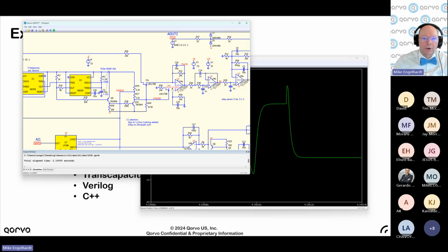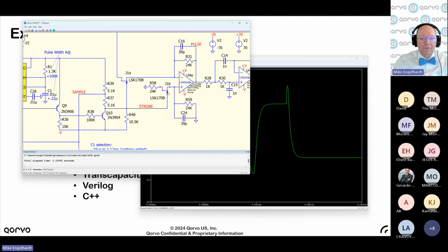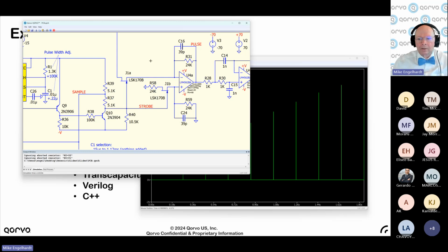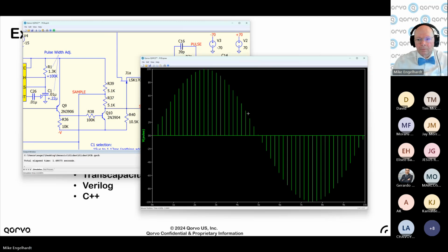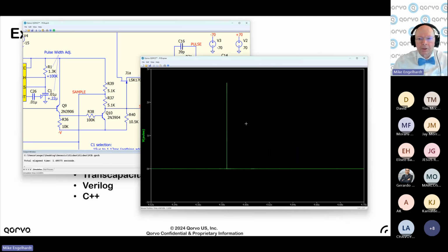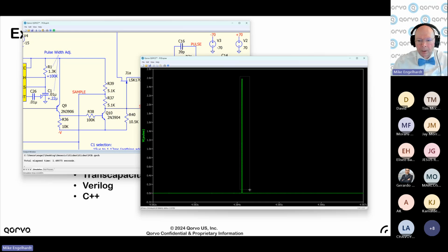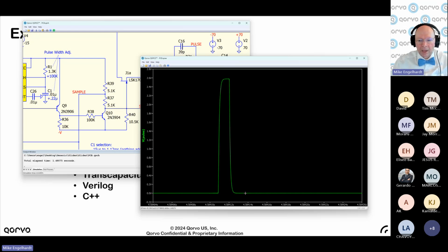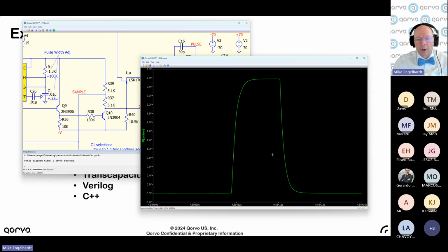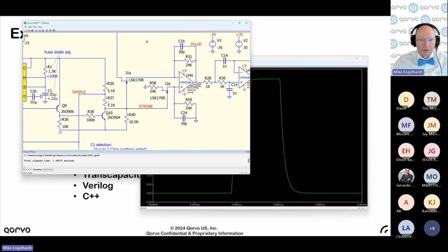Basically, on this node, instead of connecting it to ground, I mock up the same circuit on that. So if this JFET is on, this node is ground. If the JFET is off, it's still ground because it's connected to ground through here instead of through both of them. And then the charge injected cancels. So this is what the pulse looks like. So I get a perfectly clean pulse with canceled charge injection. That's just one of the uses I've used for QSPICE.